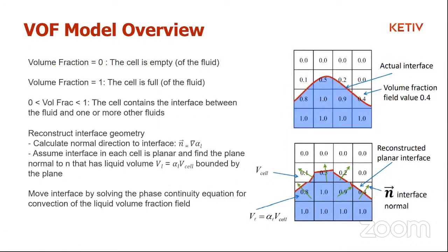Now, the previous concept was common to both VOF and the mixture model. But what is unique about the VOF model is it is used in those situations where you want to understand the shape and position of the boundary or the interface between the different phases in your domain. So for example, on the right over here, if you look at the computational grid, we are looking at the volume fraction of any particular phase.